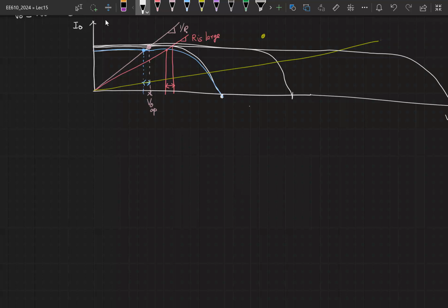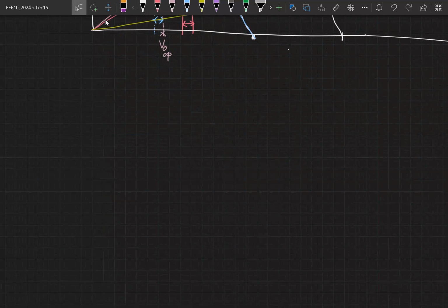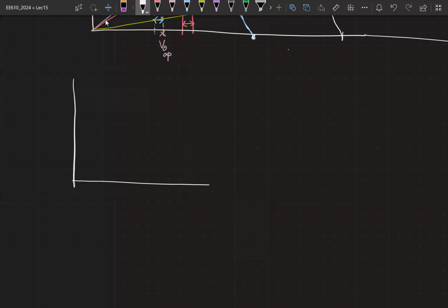So let's take a step back and see what the real requirement is. So let's say the transistor properties for a reasonable VDD is like this. And given that we want to make sure that our operating point drain voltage is away from the triode region, because on top of this we'll eventually have a small signal riding, and we don't want the transistor to go out of saturation the moment we apply a small signal.